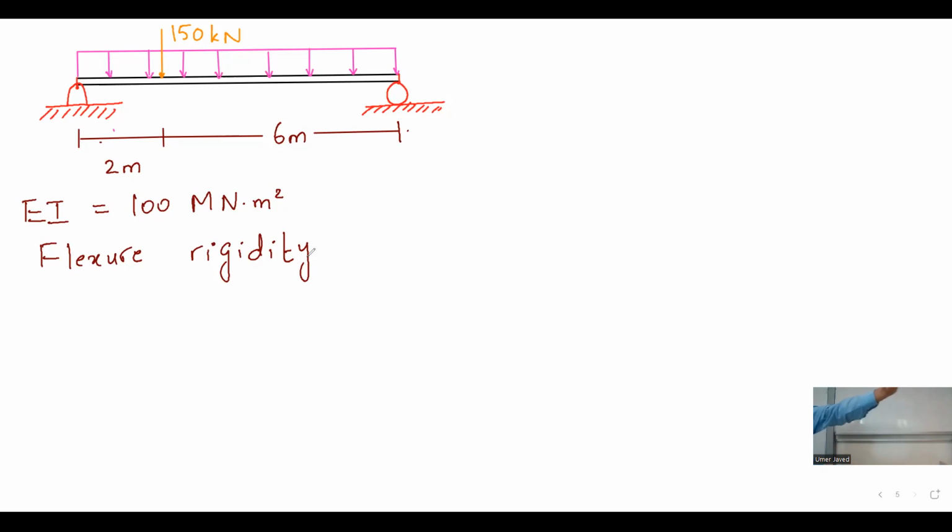But if you change this rectangular beam from this to this, so you change it from here to like this, then the deflection will be less. Of course, we know it as a fact. Similarly, if you change the material from wood to some other material, for sure the deflection will change, right? So EI has an important importance. That's why your deflection has it.